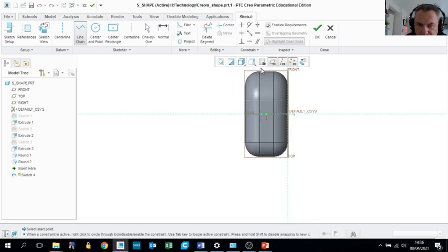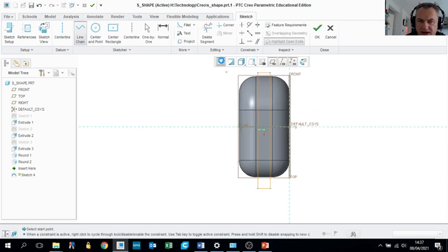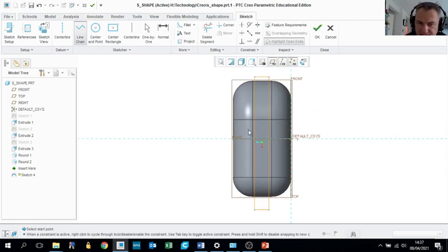And I'm going to click outside the model, go through the model with a vertical line, horizontal, and then all the way back out the other side. The blue dot appears, which means I'm level with where I started, so I can left click and connect. I can still connect it, so I have to press the mouse wheel to deselect. Okay, so what I've drawn is a rectangle on a plane.